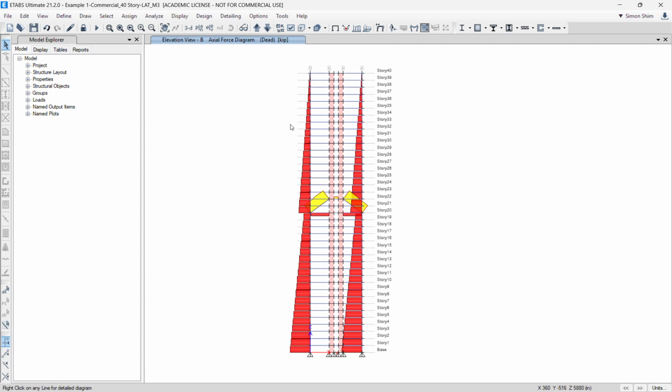When the building is topped out, constructed all the way up, we come down and make the permanent connection between the bracing and column, so that all the column reactions gradually increase during the construction. After construction is topped out and completed, we tie it together.